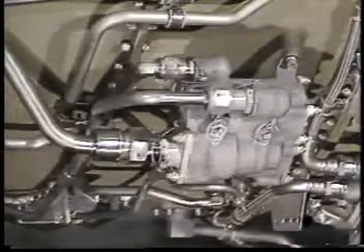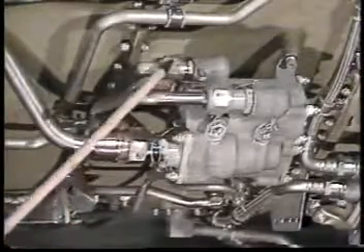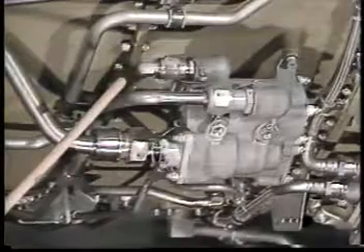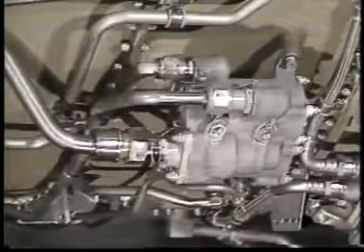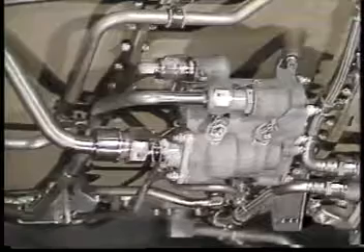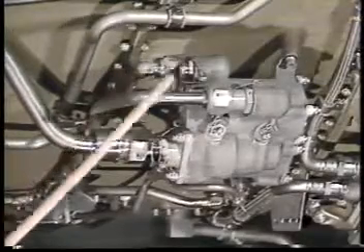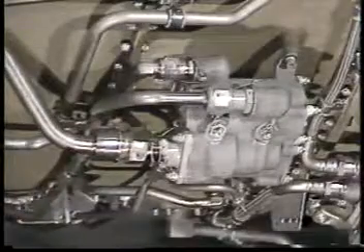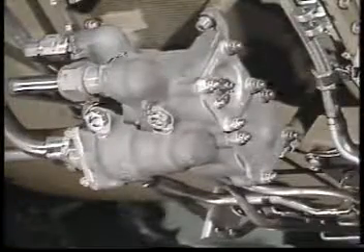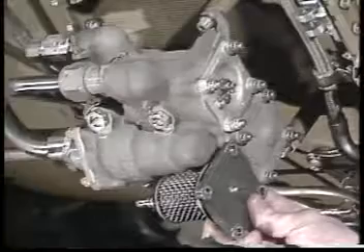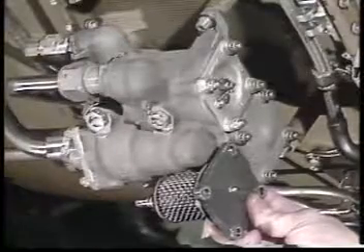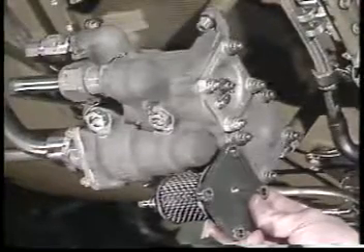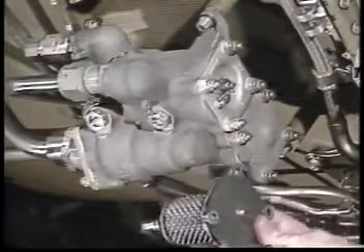During engine starting and idle operation, it supplies fuel to the primary fuel manifolds. As the engine is accelerated above idle, the valve allows fuel to flow to both the primary and secondary manifolds. An inlet fuel filter is located inside the pressurizing and dump valve housing. It must be periodically removed and inspected for contamination.